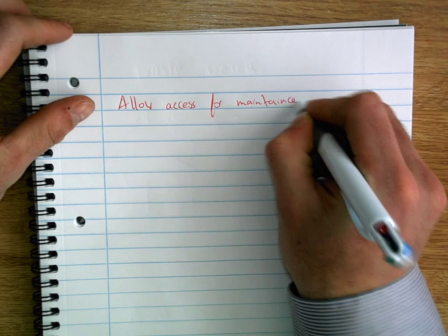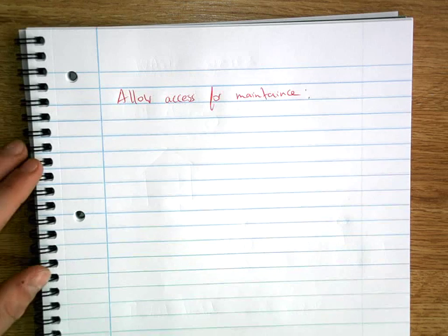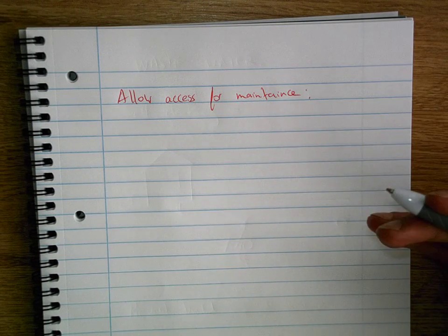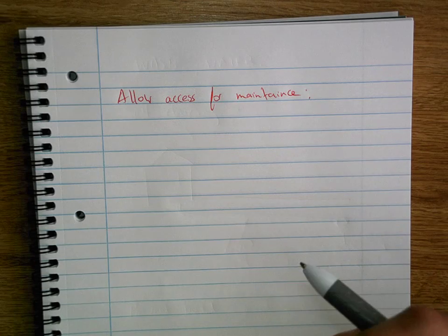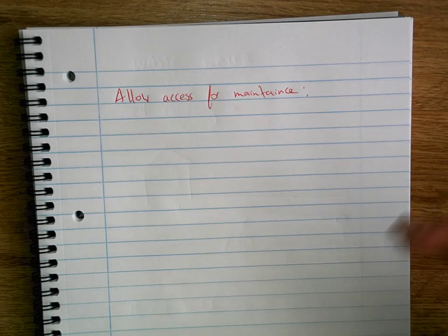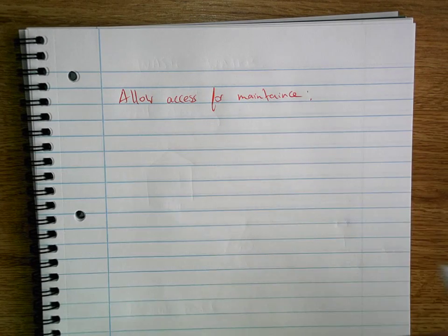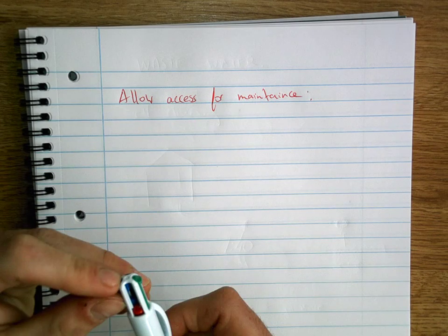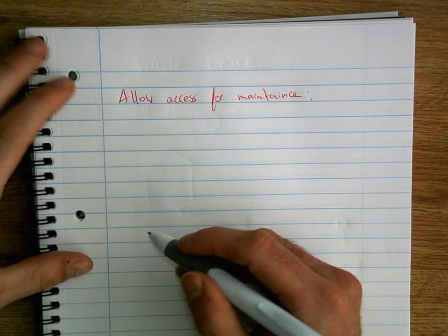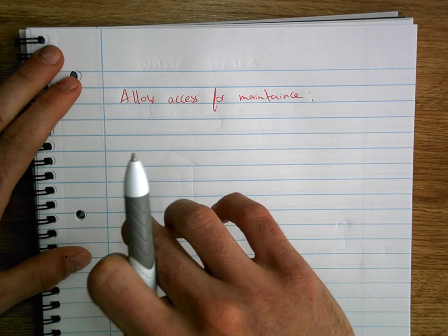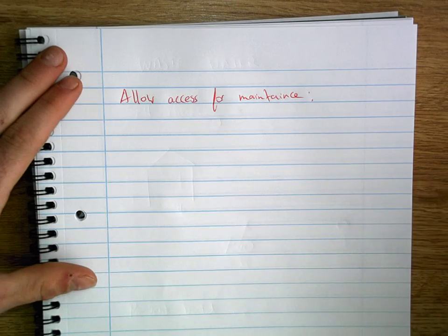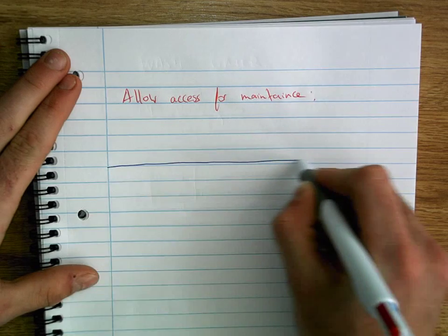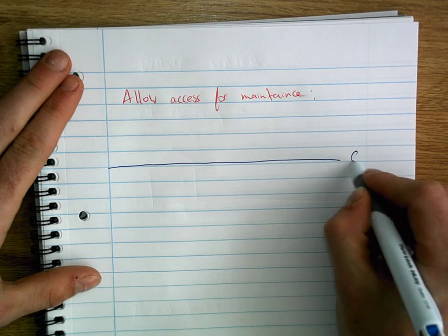Now there are 2 basic types of access that you can have. The first one, which you might recognize the most, would be your manhole. That would be for heavy maintenance that might have to take place, such as the replacement of pipes, or if there was a huge blockage in the system, you need access to a manhole. A smaller type of access, which you'll often see along these systems that are around the dwelling house before it actually gets to the main sewerage, will be what's called rodding points. And what that involves is, I'm just drawing, that'll be your ground level.